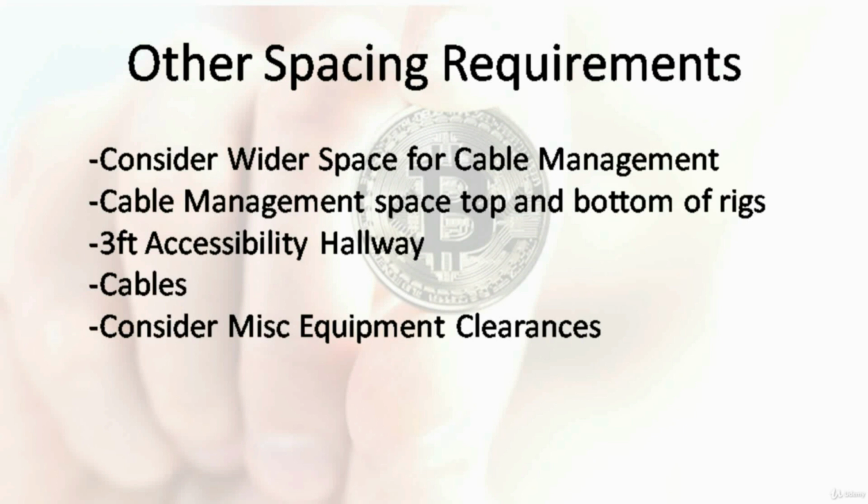Lastly, I wanted to go over other miscellaneous spacing requirements. The standard width of the cabinets is 24-inch, but sometimes you might prefer a wider cabinet solution just so that you can have better cable management. In that case, I would recommend using 30-inch width cabinets so that you can manage your cables more effectively. And speaking of cable management, you need spaces between the top and bottom of your rigs for accessibility and, of course, again, cable management.